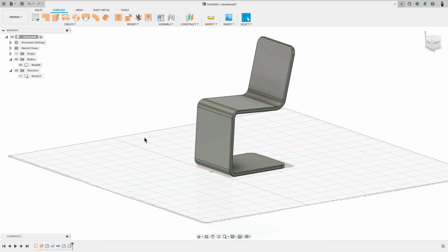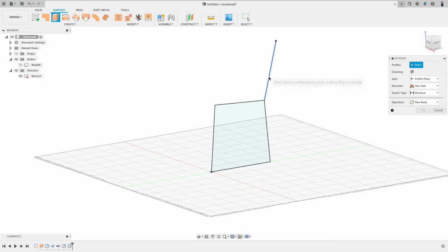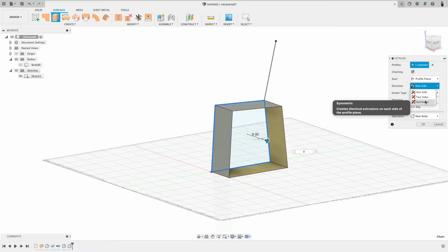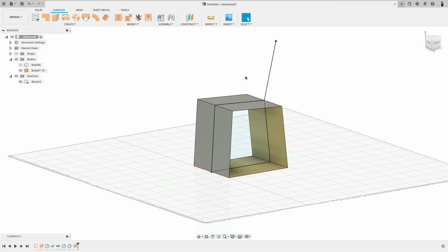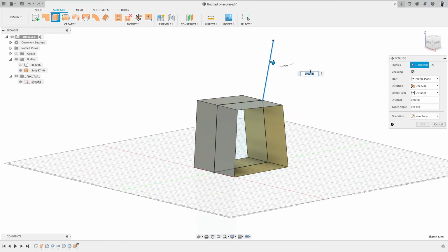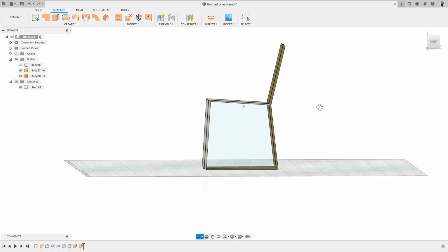And we extruded everything out of kind of like a basic sketch. Now, the nice thing about this process and this system we have, let's actually do this. We go to extrude and we will extrude here this whole thing, 8 inches. Symmetry. Very good. Then we go extrude this one here, 8 inches too. Symmetry. Good.